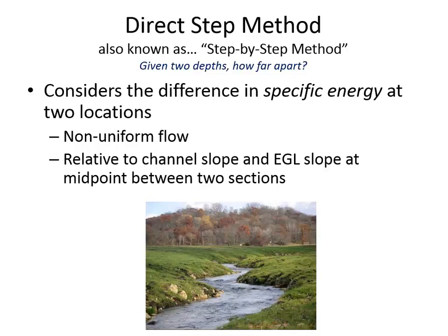But there are times where you have a water surface profile that's changing more abruptly, or you have a really long profile that exceeds the upper limit that you can apply in a single step. And so the direct step method is a way of taking multiple steps and showing it all on a single page. In the direct step method, sometimes since you've got calculators in a vertical sense that you're iterating to get the solution, you can't really preserve and display what the length of each of the different segments are.